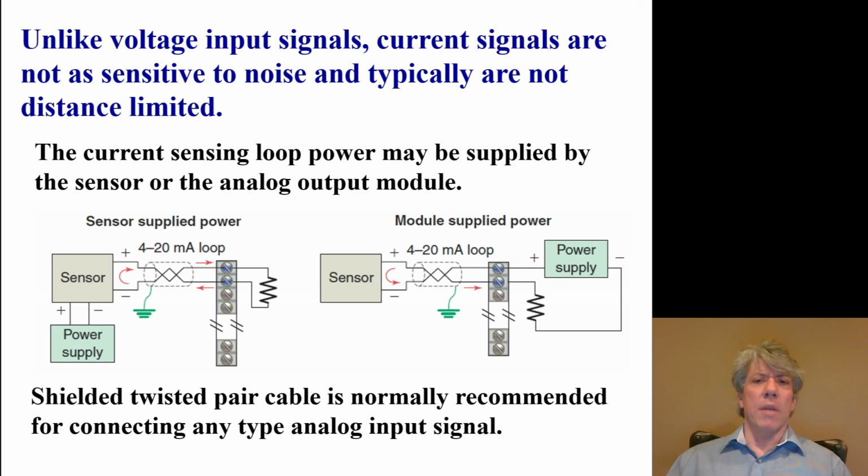Another thing to note about this is, you notice it's 4 to 20, not 0 to 20. Why would we represent, say, no pressure as 4 milliamps instead of 0? It would make more sense to have it as 0, right? Actually, not really. Think about it. If the sensor fails, then the amount of current going through the wire will be 0, and that would be a fault condition that could be recognized by the controller, by the PLC. If there's no current at all flowing through the loop, that doesn't mean that the pressure is 0. That means the sensor's broke, and that's worth knowing.